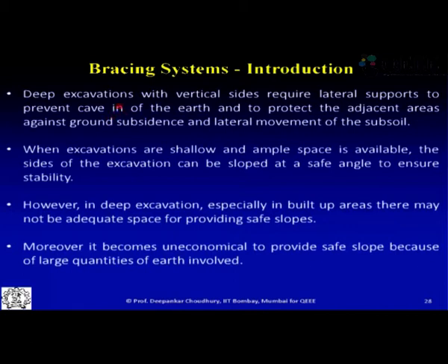Now when we go for deep excavation with vertical sides, it requires lateral support to prevent the cave-in of the earth and to protect the adjacent area where other buildings may exist, from the lateral movement of the subsoil. Now when excavations are shallow and ample space is available, then this is not required. You can provide a flat slope, which will take care of these issues of excavation.